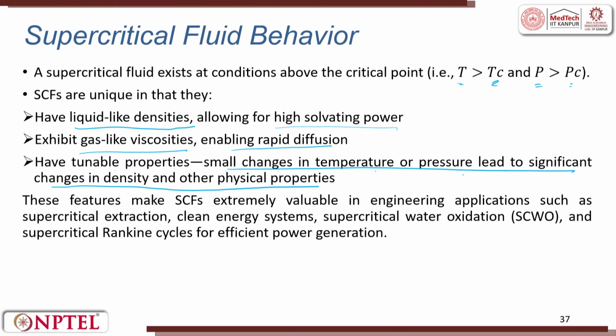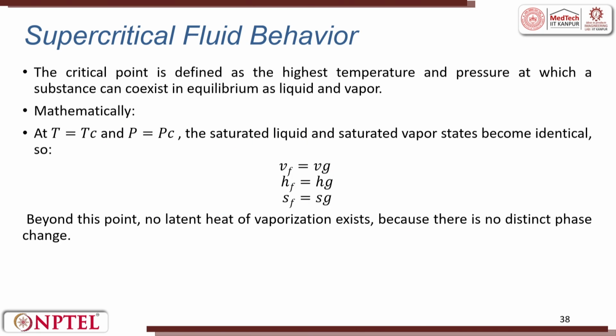These features make SCF extremely valuable in engineering applications such as supercritical extraction, clean energy systems, supercritical water oxidation and supercritical Rankine cycle for efficient power generation. So, the critical point is defined as the highest temperature and pressure at which the substance can coexist in equilibrium in liquid and vapor phase.